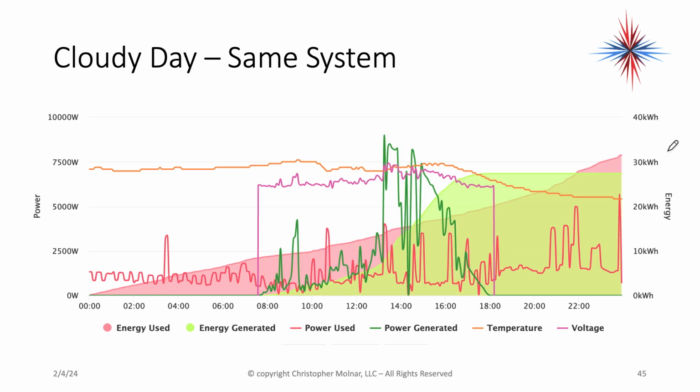The same system on a cloudy day. We may have only generated 28 kilowatts. We bought in, or used, right over 30 kilowatts. This difference here is taken out of the credit from the other days. And at the end of the month, it's all totaled up, and you only pay for what you use. Plus, of course, the minimum customer connection fee, which is like $30.